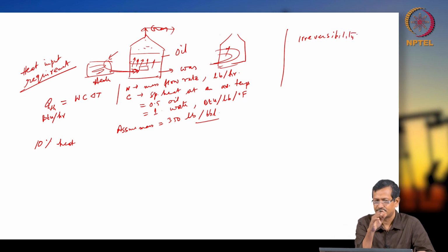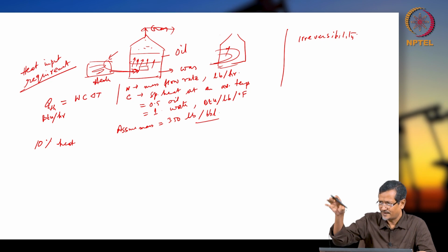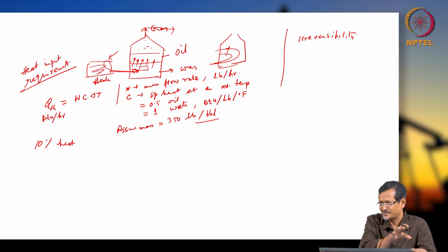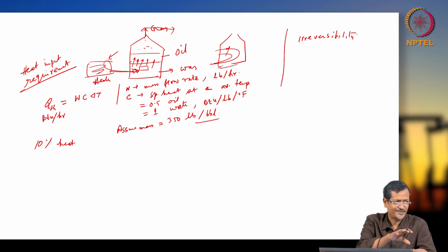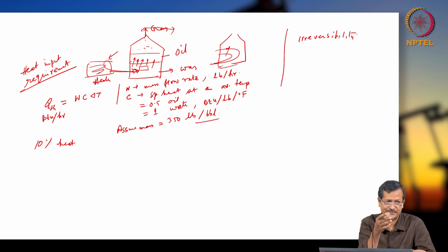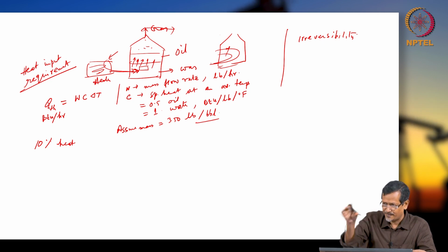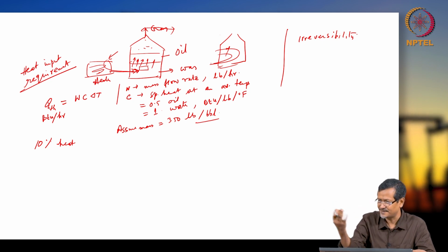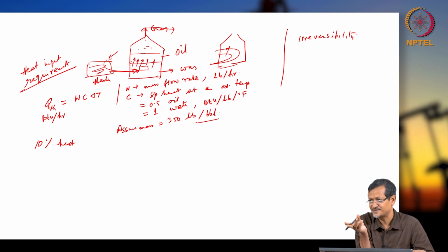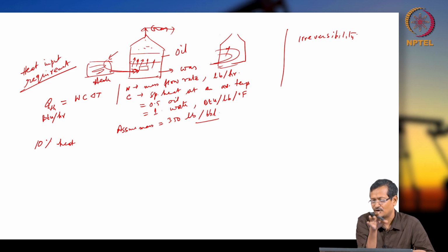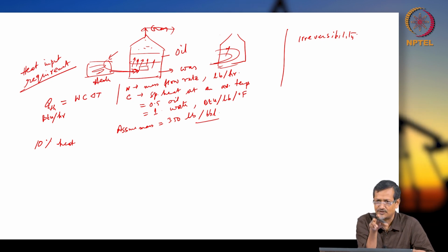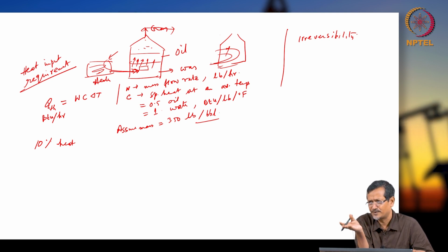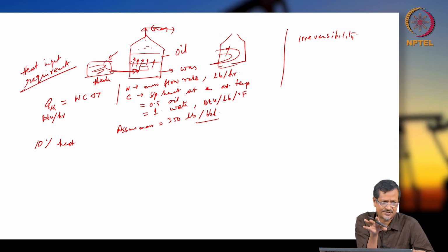Say you converted some heat into work, and again you convert the same work to heat. You cannot get the same amount of heat again, because it is lost again. So some energy will be lost. That's irreversibility. If you change back to the original system and some energy is lost, that's why it is irreversible. But if you get the complete energy back, then it is reversible. So the second law, or Clausius statement I think, says that if you are converting one form of energy to another form, a certain amount of energy will be lost.